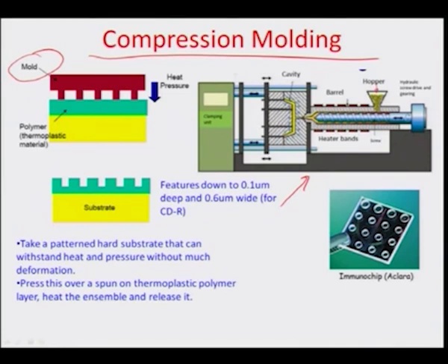So, that the idea is that you can separate whatever is formulated here. Whenever the polymer melt goes into this area as a low temperature zone, it immediately solidifies and retains the shape of the die.